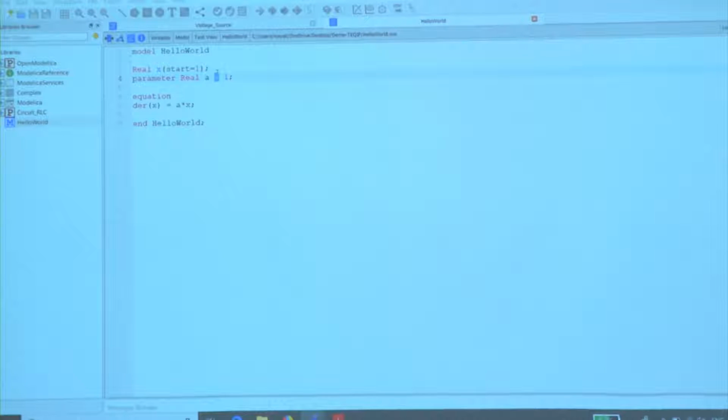So why do we need Modelica for this? To answer that question, Modelica is mostly suitable for physical modeling. When I say physical modeling, to give you an example, let's take a very basic RLC circuit. Let's say I want to simulate an RLC circuit in OpenModelica. With any kind of block-oriented approach, you will have a sine block, a capacitor block, different kinds of blocks, and then you connect them, and it's a bit confusing.